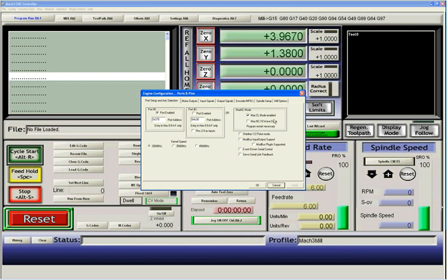The next thing that we can see on that screen is that the Mach mode is enabled. These modes under Mach NC are only for a particular type of machine, and they change the output characteristics of Mach 3. Instead of step and direction, for example, Mach mode is a quadrature output. It puts out an A and a B signal, much like an encoder does, and this causes the motor on a Mach CL to move. So we have to turn it off.